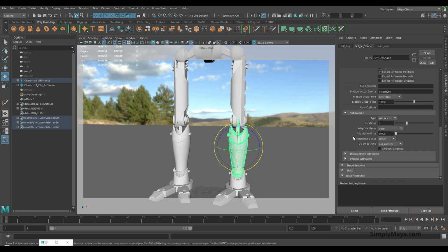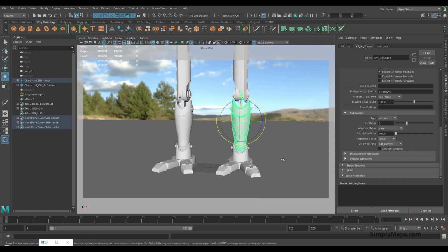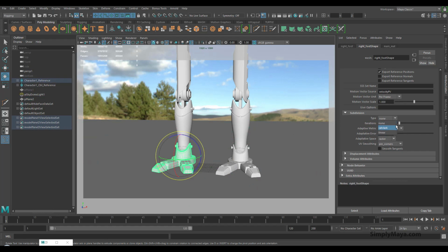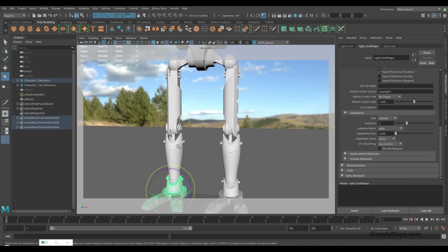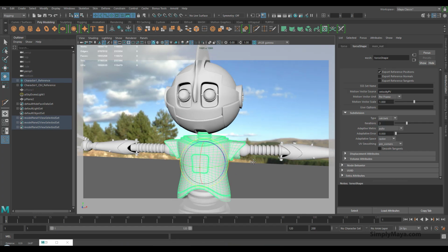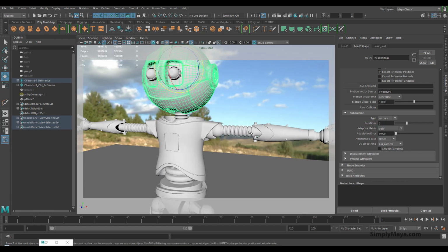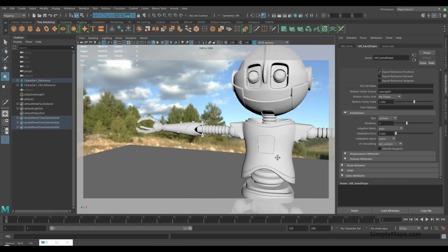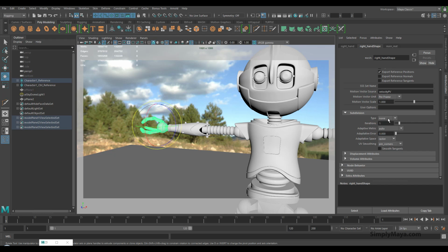Now the first time you do a render with displacement like this, it's probably going to take a bit longer than the second time you do it, because Maya and Arnold are going to calculate all that displacement. So you'll get a few minutes of delay the first time you go into this, but after that it should be fine. It should render fairly quickly. Now that will change, of course, if you change the subdivisions or you change the displacement file itself.